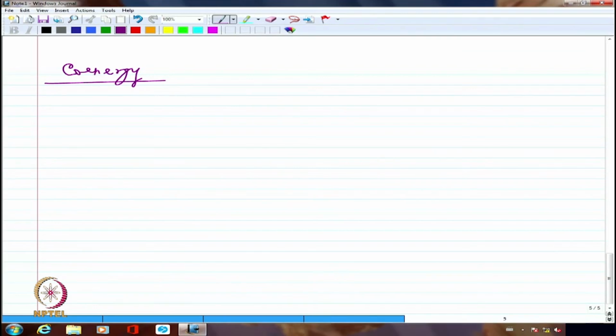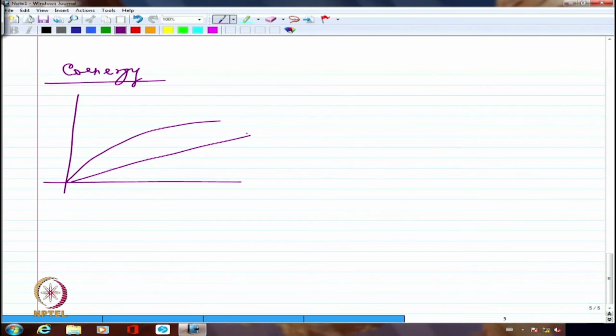Right? So let us say I have a magnetization characteristic like this. This clearly indicates that I am drawing the magnetization characteristics for an iron core along with maybe some air gap. If it is only associated with a large amount of air gap, it should have been linear. If I reduce the air gap further and further, it will go further and further towards non-linearity.